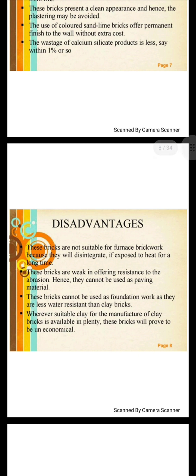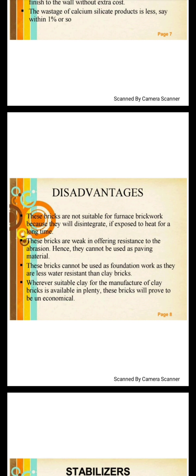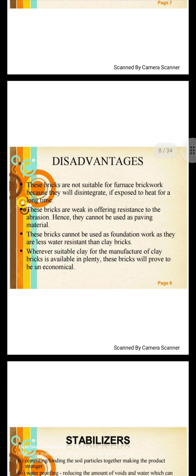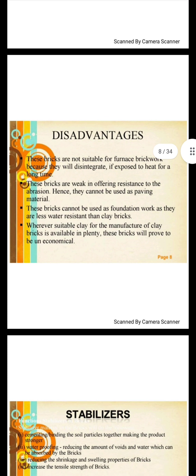Now the disadvantages of this type of brick. These bricks are not suitable for furnace brickwork because they will disintegrate if exposed to heat for a long time. These bricks are weak in offering resistance to abrasion, hence they cannot be used as paving material. These bricks cannot be used for foundation work as they are less water resistant than clay bricks. Wherever suitable clay for the manufacture of clay brick is available in plenty, these bricks will prove to be uneconomical.